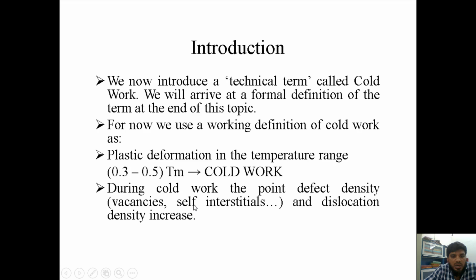So the cold worked material is harder but it is brittle. This has to be noted. This is the important point in cold worked materials. Even though the material becomes hard, it will be brittle. So once it breaks, it will not undergo any plastic deformation. It will just break into pieces.